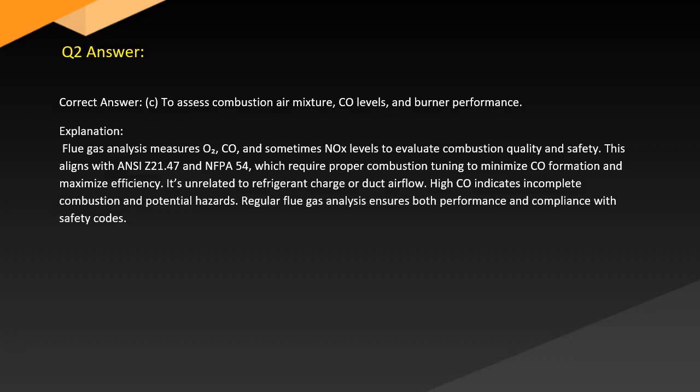It's unrelated to refrigerant charge or duct airflow. High CO indicates incomplete combustion and potential hazards. Regular flue gas analysis ensures both performance and compliance with safety codes.